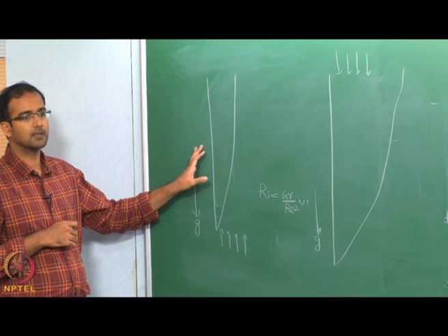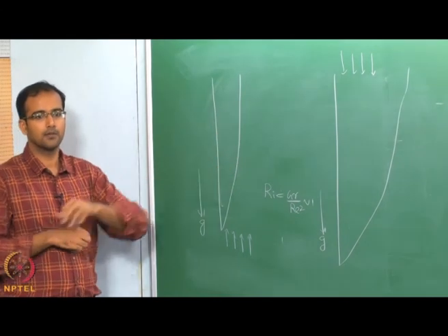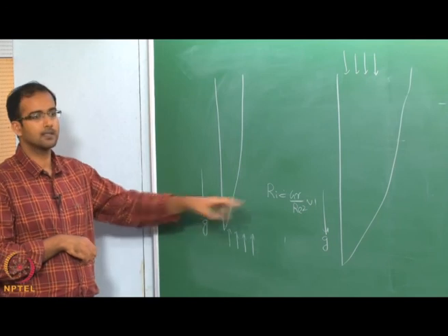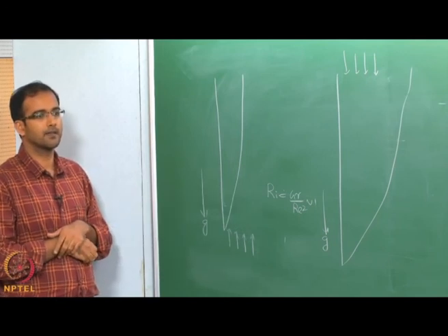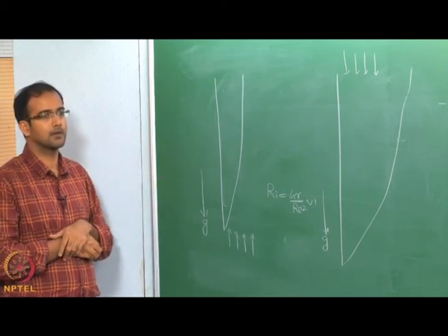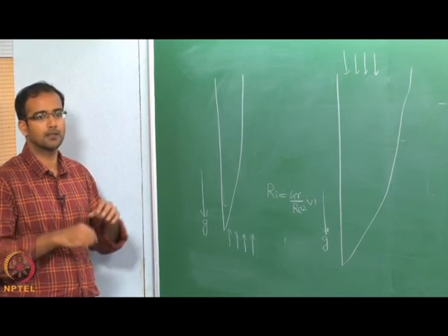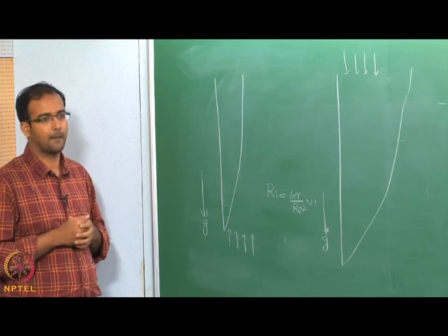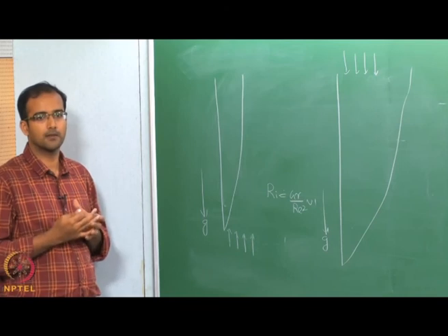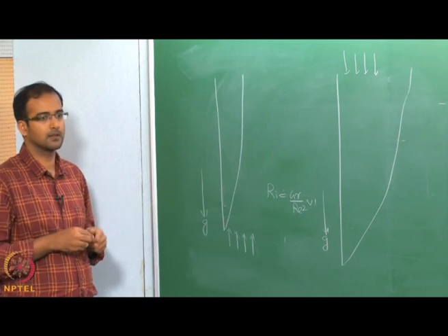But for the limiting cases, for very small Richardson numbers, there the forced convection similarity variable might be the correct one. And similarly, if you go to the other limiting case where the Richardson number is very large, there using the Grashof number in the similarity variable might give you the similarity solution, but these are only in the limiting cases. Okay, but most of the regimes where both are dominant, we cannot find any similarity solution to this. Again we have to go for numerical solutions.